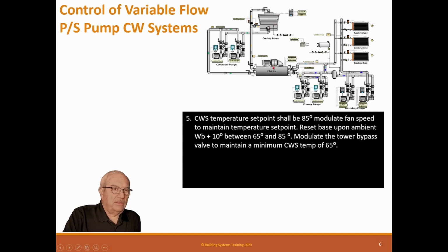So basically, running this down is good. And we're using 10 degrees. That may be adjustable. You may want to go colder than that. But the reason we're using 10 degrees is basically I live in a dry climate, where I have very low wet bulbs, and I don't want to get that cold, so we keep the 10 degrees. So basically it depends on where you're living, where the system is at.